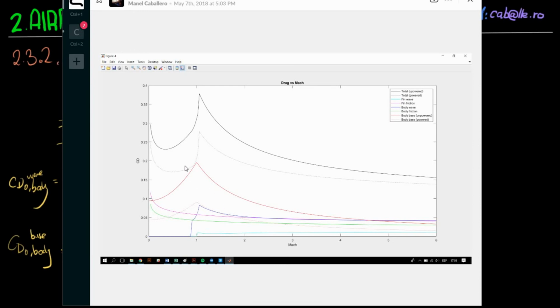But this is a very nice plot. You can see here that if we have geometry fixed, it's very nice that actual drag only depends on Mach. Kind of. There is the dynamic pressure, which isn't quite Mach, but still.